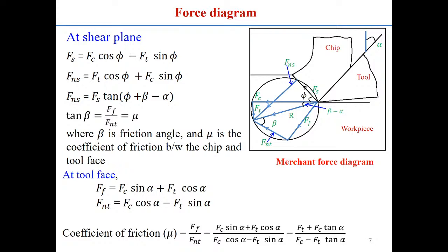So along the direction of the linear velocity of the tool, one particular direction, and in the same direction we represent the cutting force. When we estimate the power requirement, we know force into velocity represents the power. So cutting force into velocity represents the power. That is the relation we are getting. Now, making the force balance in different planes, we reach all these kinds of conclusions.